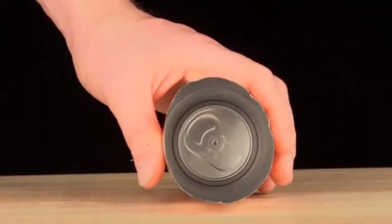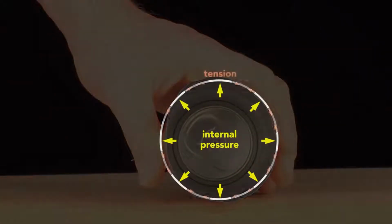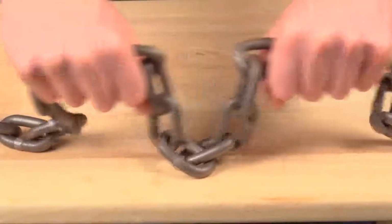But the internal pressure of a sealed can pushes outwards equally and so keeps the wall in tension. This tension is key. The thin wall acts like a chain. In compression, it has no strength, but in tension, it's very strong. The internal pressure strengthens the cans so that they can be safely stacked.